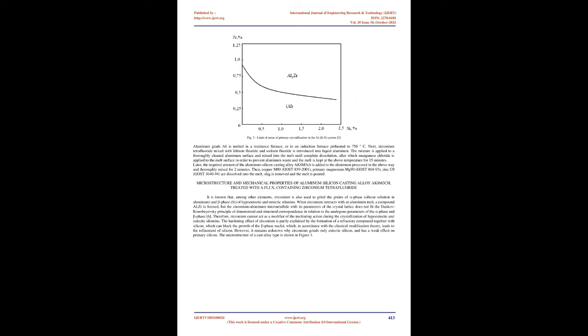When carrying out the preparation works, the use of tools made of titanium is recommended. Charge materials cleared of dirt, oils, and oxides are loaded into the furnace. Firstly, large pieces of the charge are placed on the bottom of the crucible, and then the space between them is filled with small pieces. It is known that the addition of silicon to an aluminum melt significantly reduces the amount of zirconium, which can be dissolved in liquid aluminum and prevents the saturation of aluminum with zirconium.